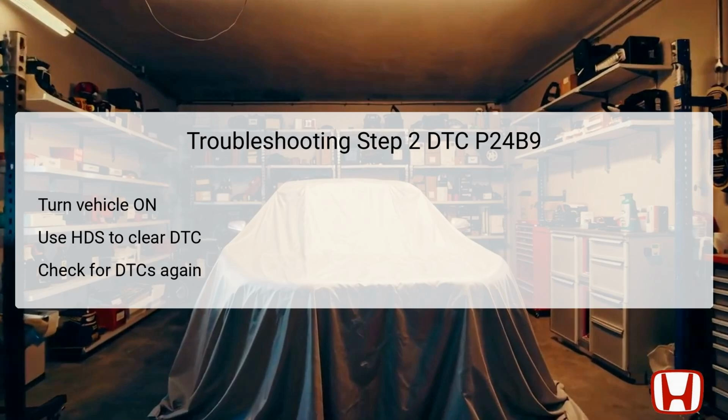The next step involves checking for any pending or confirmed DTCs using the HDS. If DTC P24B9 reappears, it confirms that there is indeed an issue that requires further investigation. If it does not return, the system may have had an intermittent failure, pointing to potential issues with connections or terminals instead of a direct component failure.